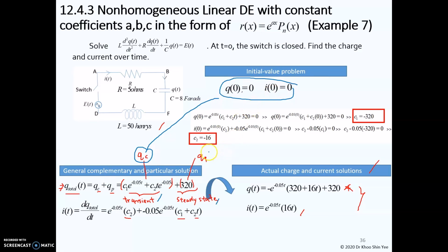On the other hand, the particular solution is the response due to the right-hand side function here, which is the forcing function. In this case, the electrical voltage supply from the battery or the generator is the forcing function. In simple terms, the transient solution here will happen in a short time. We will see that at t approaching infinity, the exponential of negative infinity here will become 0.